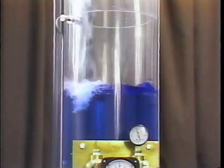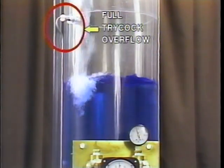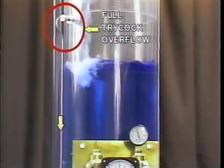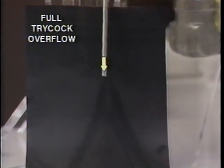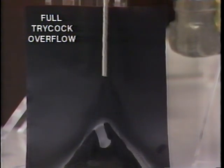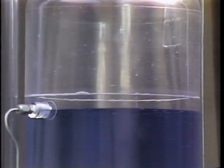We'll continue to fill in this mode until the full trycock overflow level is reached. The full trycock is the maximum level to which a tank should be filled. To go any higher could create abnormal rates of pressure rise in the tank, resulting from insufficient vapor space to accumulate boil-off gases. Let's observe what happens to this liquid if it is allowed to sit for several days with no product being withdrawn.